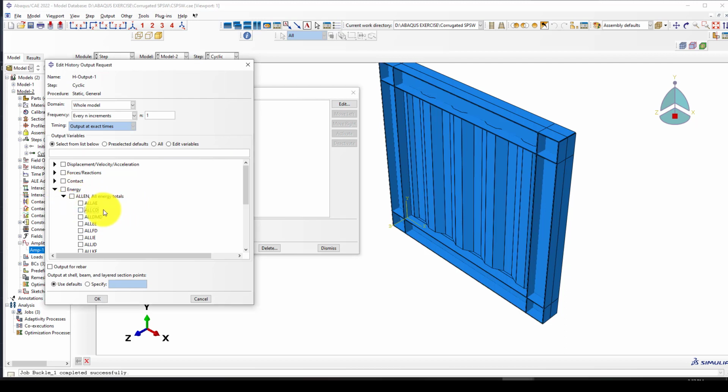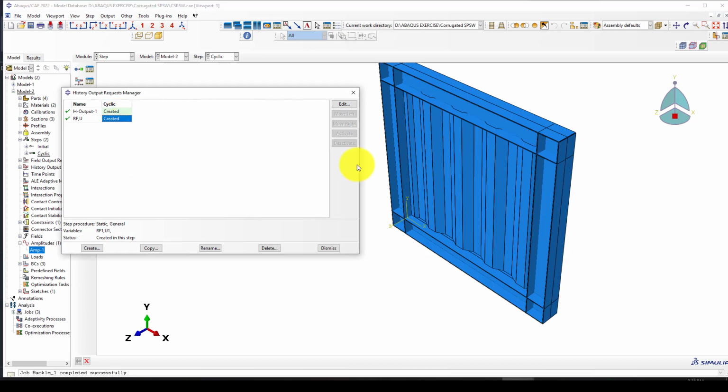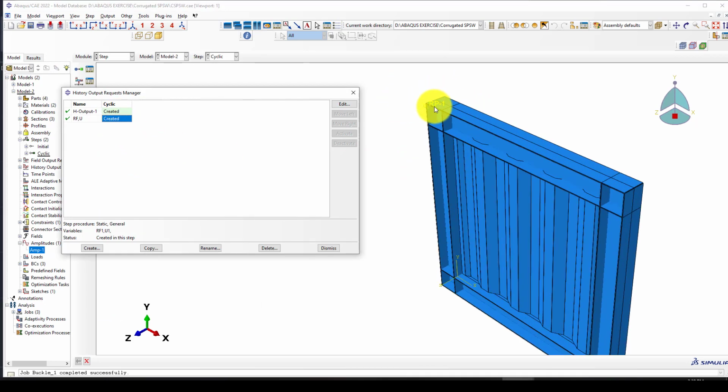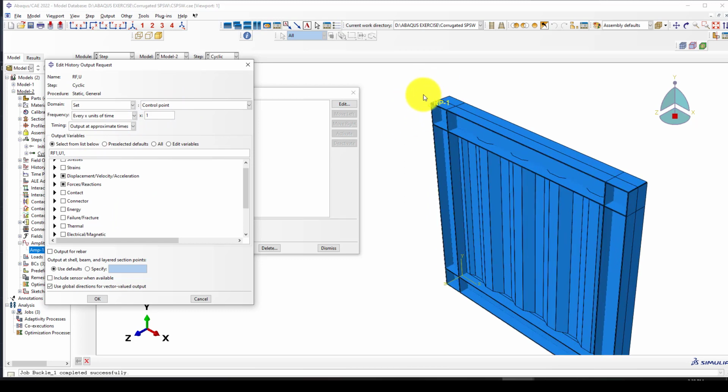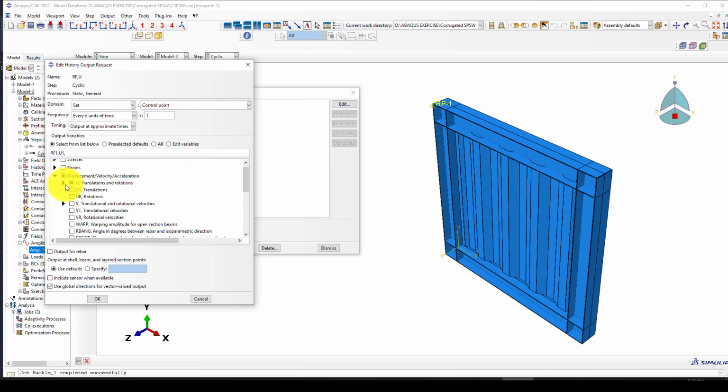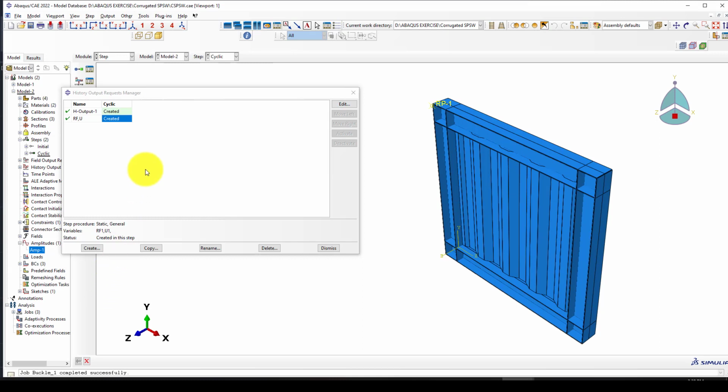So I'm going to use this, let me use PD and this elastic and total energy. You can also constrain energy as well. And now here, we previously defined this point as a controlling point, and we want to use that controlling point to get the reaction force and displacement from that point. So therefore we select the U1, which is this direction, and RF1, which is in this direction, the horizontal reaction force.